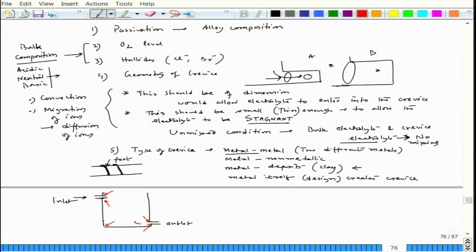In fact, if you see this is another crevice, here another crevice is forming. Okay. So, those are the crevice parts, and these parts are forming because you have not made any different metal contacts or different metal making a crevice, rather the same metal is creating it. For example, this particular bottom of the tank, this is a crevice.